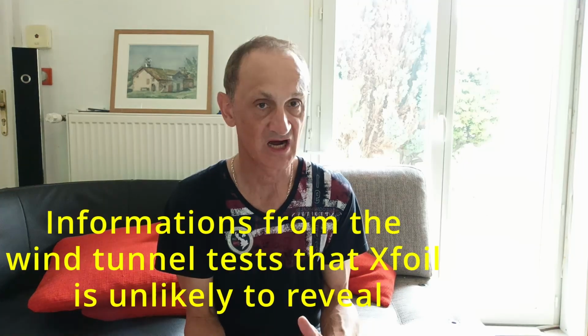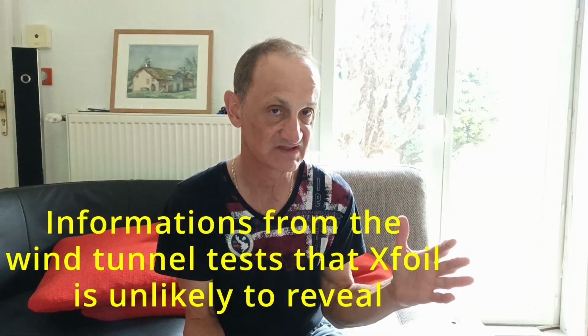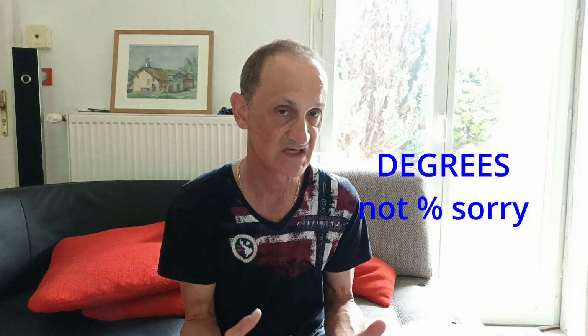And also, generally when you use Xfoil and set some flap, after 6, 8, 10 degrees you start to see that there are convergence problems in Xfoil and you cannot export the result. And I don't even speak about flaps at 20 or 40%. The value of this wind tunnel test is that we have feedback on what happens at 20 or 40% minus or plus. And that's something that you cannot have in Xfoil.